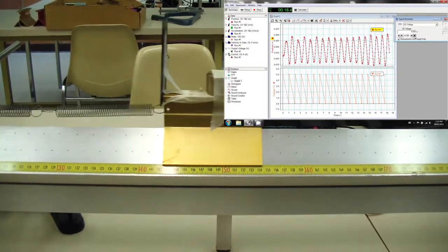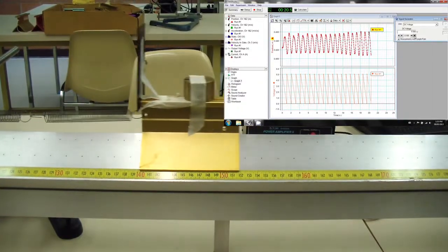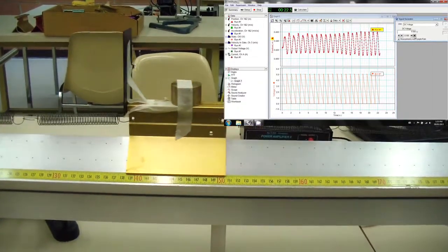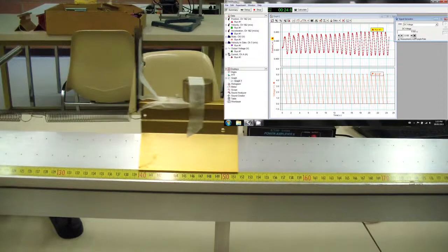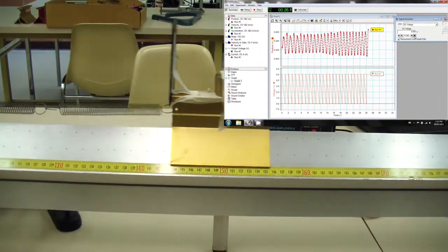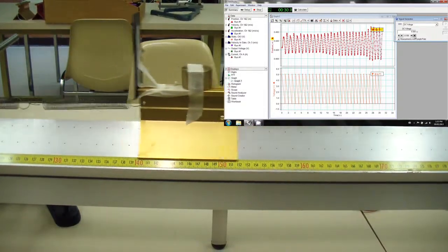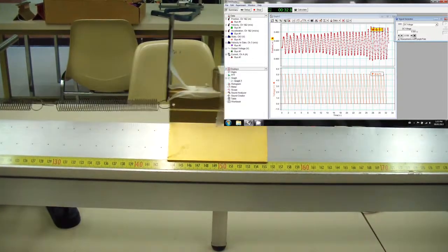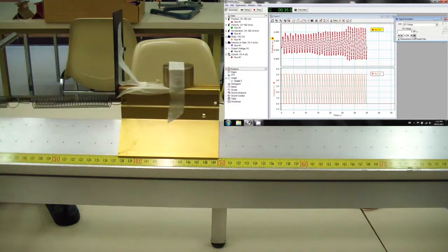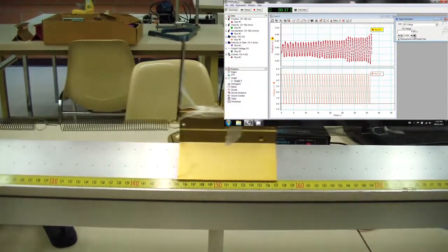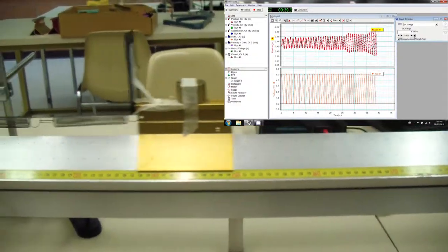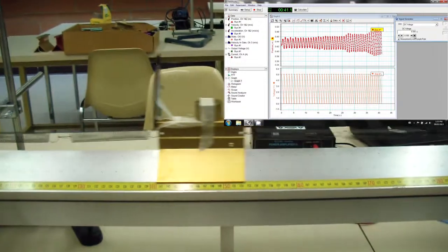To ensure that your resonance frequency is reasonable, set the power amplifier to about 2 volts and press Start. Collect a few seconds of data, raise the power amplifier output by 0.5 volts, and repeat as far as possible until you hit 10 volts. As you approach resonance, you should see the amplitude increase with each step.